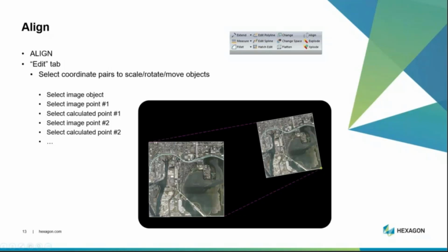There are a couple of different options for PDF import for background imagery if you want to bring one of those in and have that as background imagery while you're calculating through it or something like that. That works pretty good. You can see if you've made any errors because theoretically that plan is to scale, some sort of scale, and if you get a few lines in there, you can line it up and just work over top of it and make sure that everything's in the right ballpark.